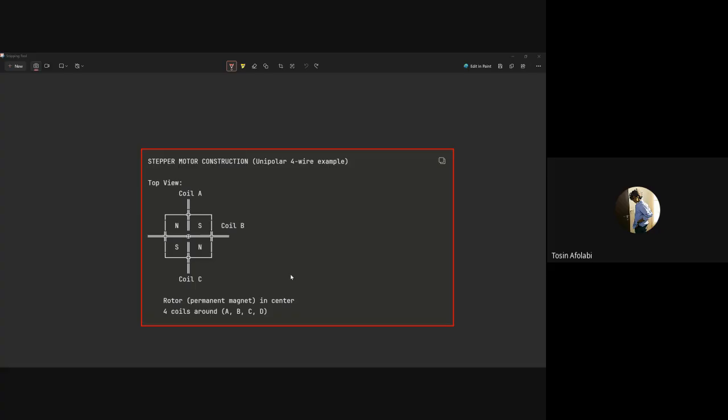Arduino pins cannot actually provide enough current to reach the speed and accuracy you're looking for, because I think Arduino pins provide 40 milliamps maximum per pin. Let me check. Yes, it should be 40 milliamps. That's the maximum they provide per pin.